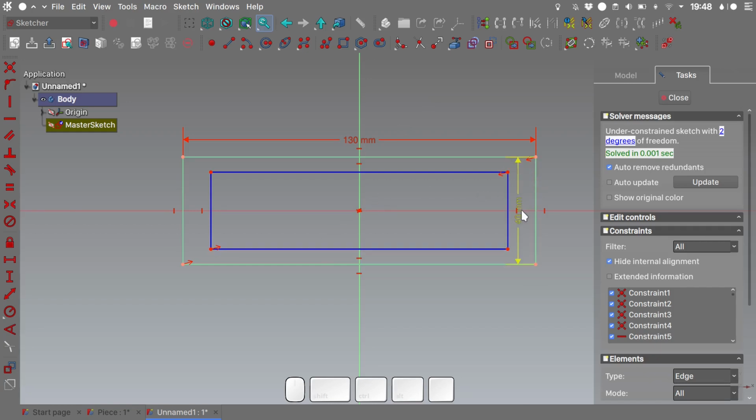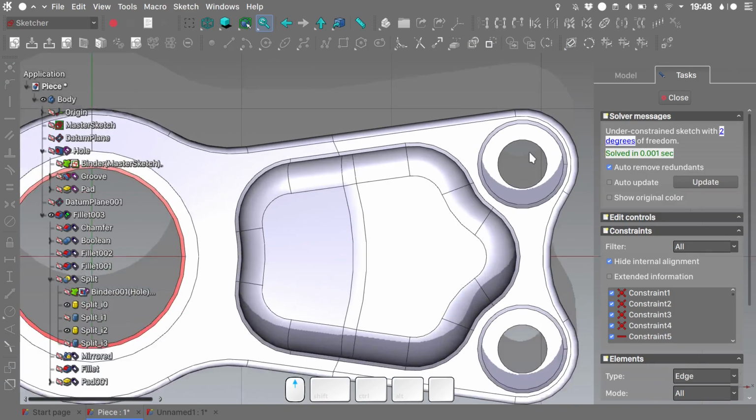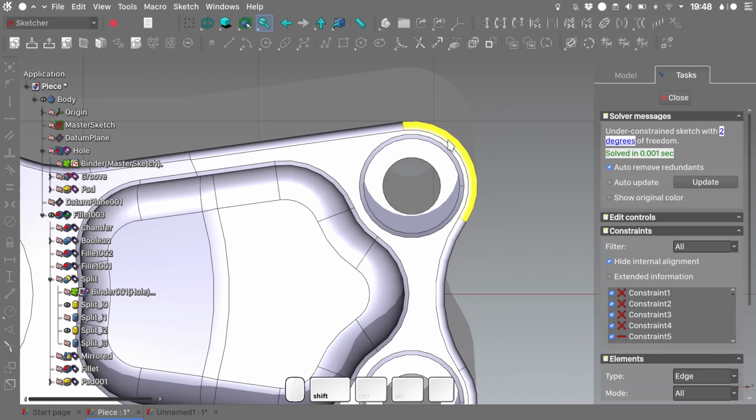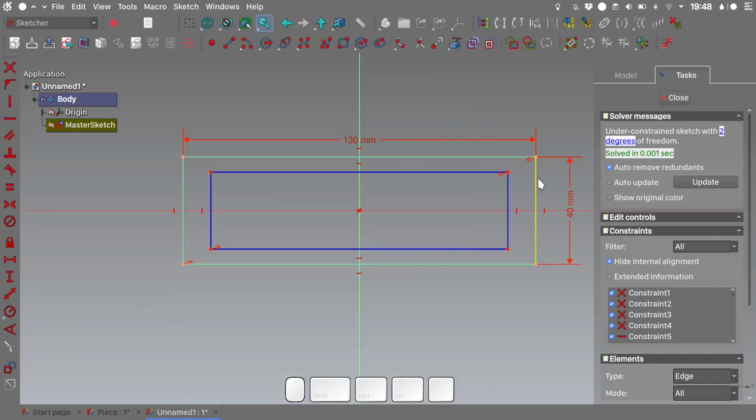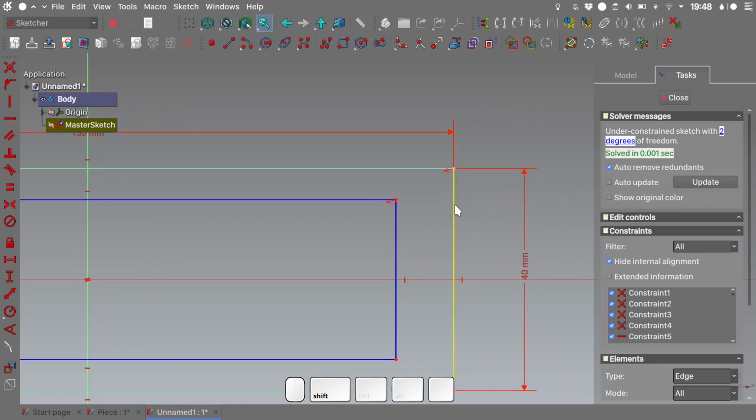Now we will use a little trick to represent what is essentially the radius of this outer arc here. So let's get back to our drawing. I will create a construction rectangle that is constrained to these 2 vertices, this one here and this one here.